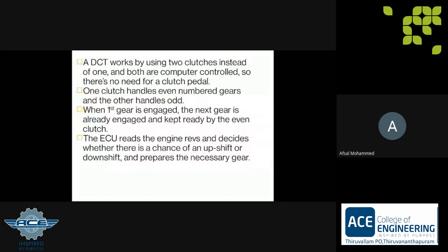This has been seen in the Volkswagen Polo GT TSI edition, which uses a DCT gearbox. And many owners have complained of lesser clutch life and also mechatronic failure in these types of transmission. And these are not exactly the most reliable ones. And the brand Volkswagen themselves have shifted to a torque converter automatic in the newest or latest iteration of the Polo.